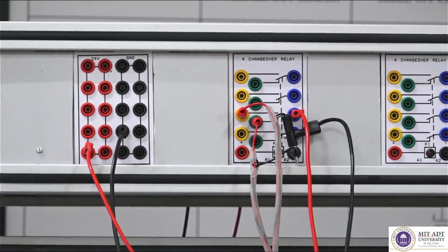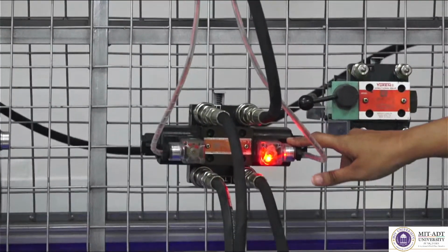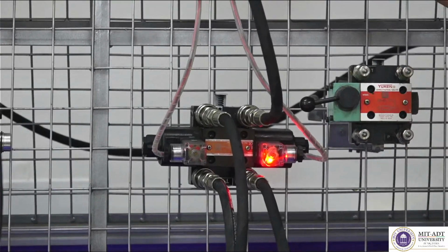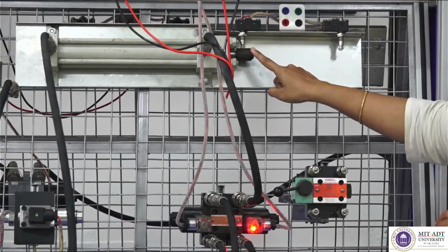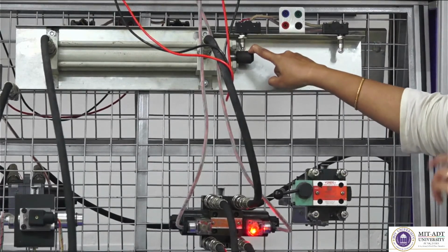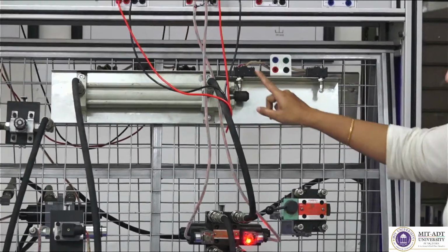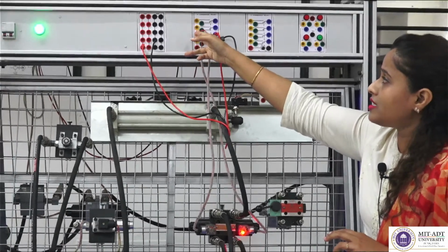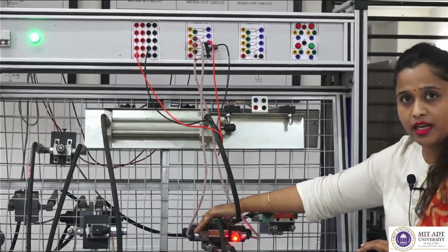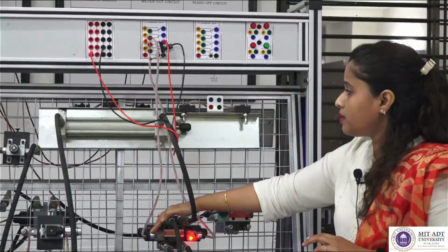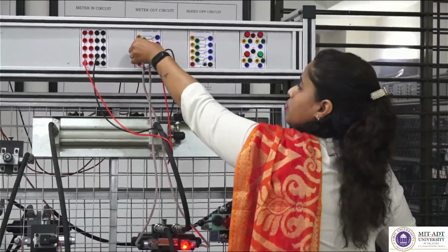So, here you can see that now this solenoid has been energized. This solenoid is for the retraction stroke of the cylinder, and as your cylinder has been already retracted, it is not showing you any position. What I am doing is, I am switching the NOs and NCs. I am flipping this NC into NO and NO into NC. Then you can see that this solenoid would be energized, and at the same time just give it a look towards the motion of the cylinder.